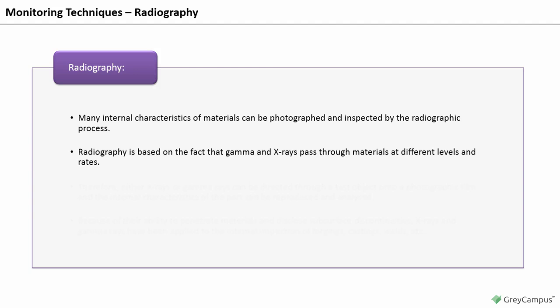Radiography. Many internal characteristics of materials can be photographed and inspected by the radiographic process. Radiography is based on the fact that gamma and X-rays will pass through materials at different levels and rates.